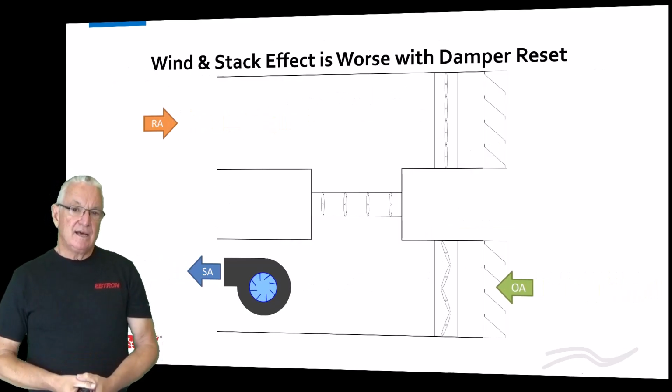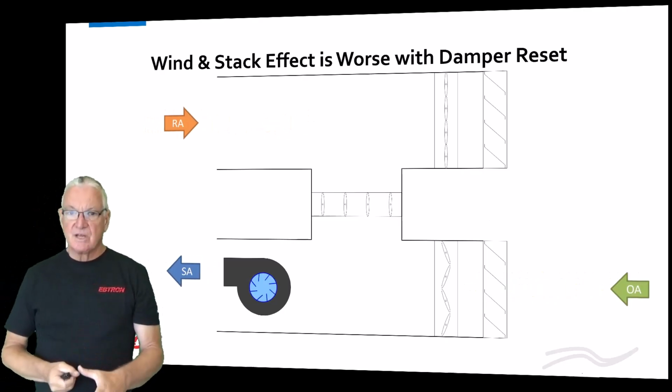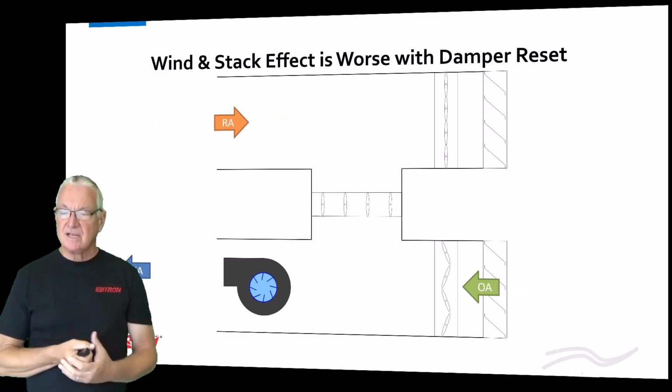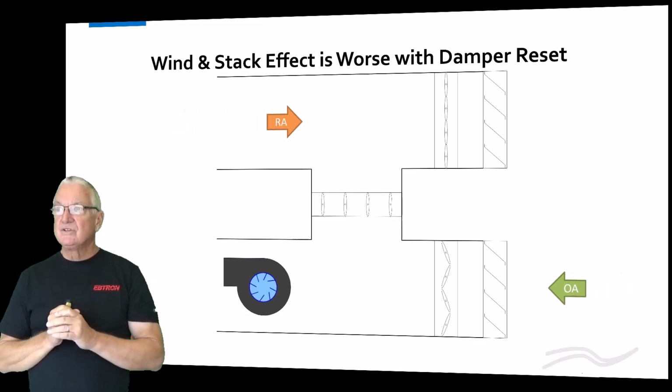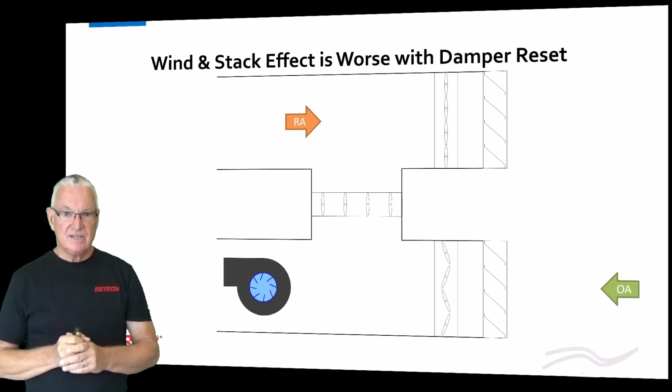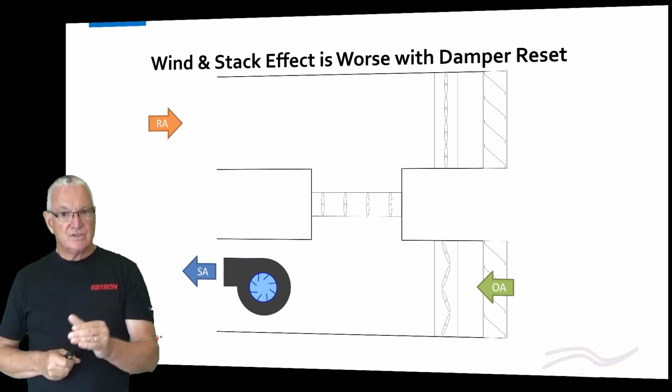All right, and I just throw this slide in just to think about it for folks. Some people say, oh, I reset the damper to compensate for fan speed, or it's a little bit different, but I use 2 damper positions for my DCV strategy. Keep in mind that everything I showed you is based on the flow coefficient of that intake.